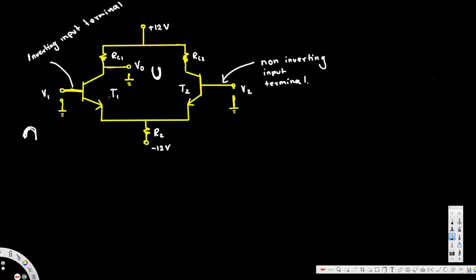Now let's look at the characteristics and the modes. There are two types of modes for differential amplifiers: differential mode and common mode. In differential mode, the V output is AV, the gain, times V1 minus V2. Sometimes if the polarity is opposite, we have V1 and minus V1, equal magnitude, opposite polarities. In that case, we get the V output to be AV times 2 V1. This is for differential mode.